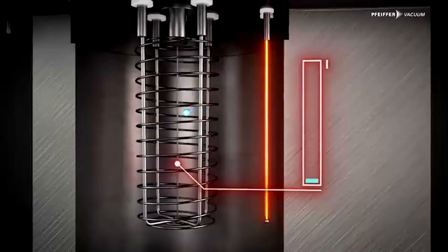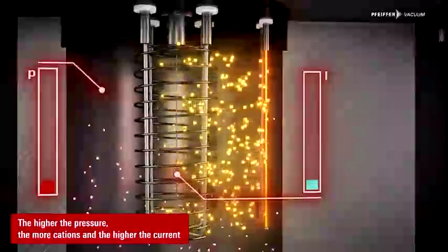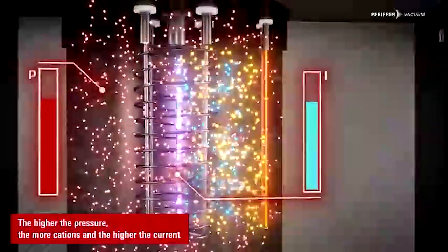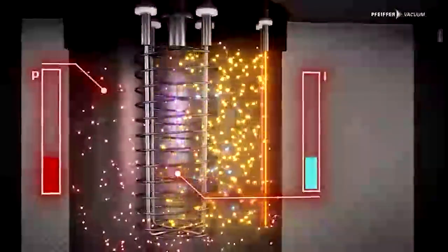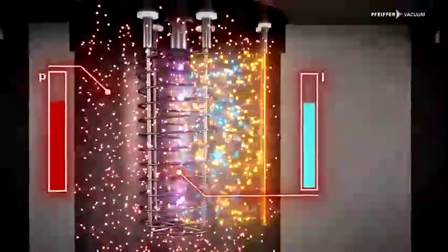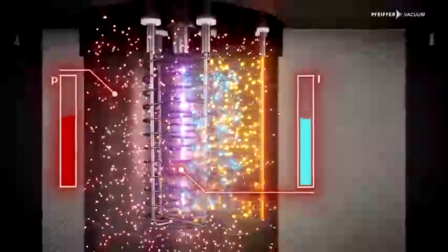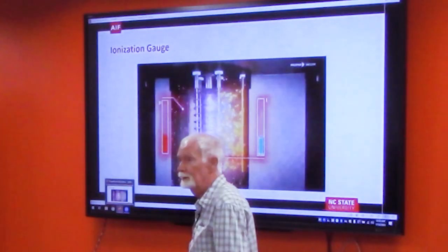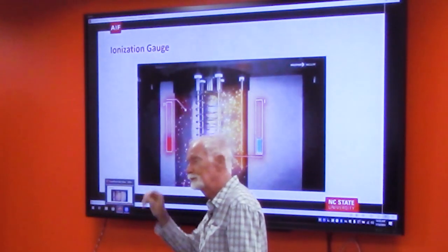This is a very reliable gauge in terms of measurement. The Bayard-Alpert gauge has some issues. The cold cathode gauges have some issues. That's why I like this one, if I want a measurement I can trust. What's the catch? You've got a filament in here. Has anybody ever opened a vacuum system to air with the filament on? But they now make these with thoriated iridium filaments, and they're much harder to burn out. The other ones, you just see the smoke and a gray cloud in your vacuum chamber.